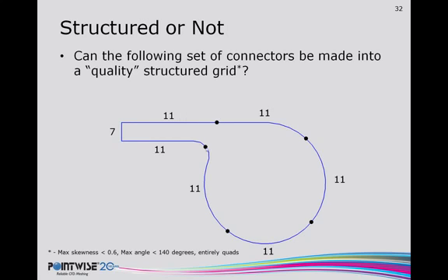The first thing that jumps out at me when I look at this is this inlet shelf here. This is a roughly rectangular region, so if we just introduce a connector across here, we can put a regular H domain in here without much issue at all. So that's the first step: get the easy parts and whittle away at it.